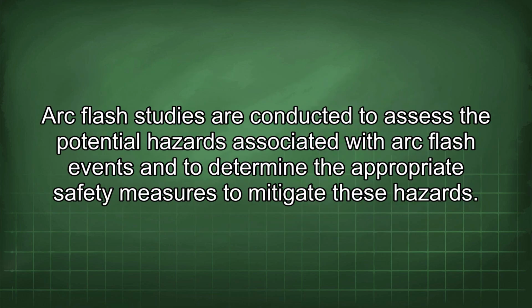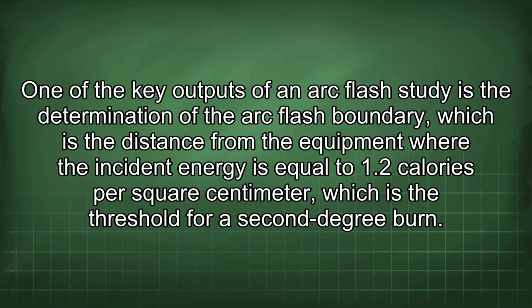Arc flash studies are conducted to assess the potential hazards associated with arc flash events and to determine the appropriate safety measures to mitigate these hazards. One of the key outputs of an arc flash study is the determination of the arc flash boundary, which is the distance from the equipment where the incident energy is equal to 1.2 calories per square centimeter, which is the threshold for a second-degree burn.